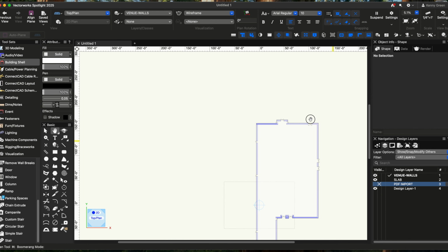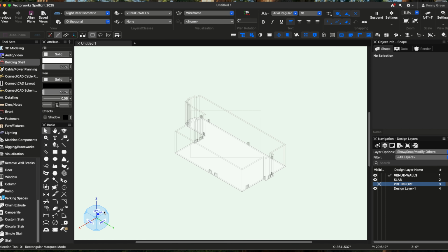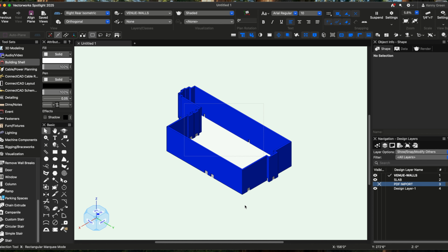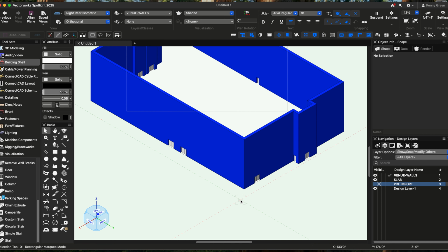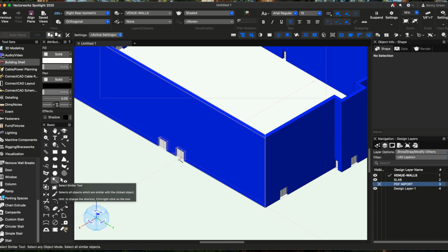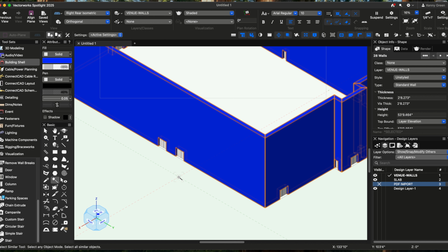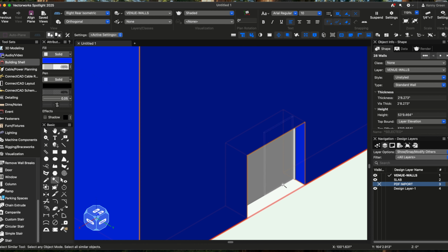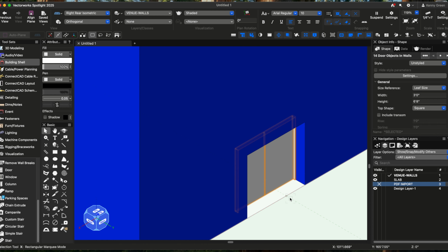Now let's turn the PDF layer off, so we can now go into a right ISO view and we can show you what it looks like. The walls all scaled with doors. And there we go. Now you can leave the doors open or closed. So if you want to open them, just pick your select similar tool, click on one of your doors, not your walls. Zoom in here a little bit tighter. There we go. It says there's 14 doors in walls.